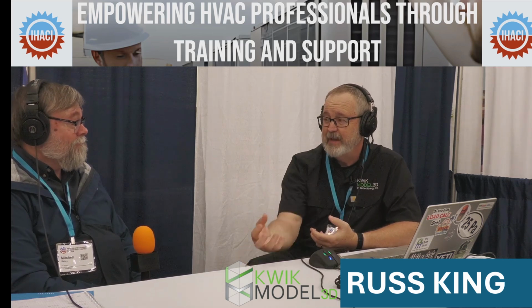Sure. The way I see it, load calcs are something they should be doing. To me, it's not professional to install equipment in a house without really knowing what the house needs. A lot of people say, well, it had a 4-ton before. So they're trusting the person that originally designed that, and you're assuming that the house has not changed in 20 years. And that's a bad assumption.